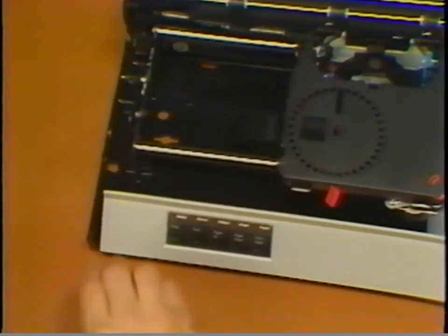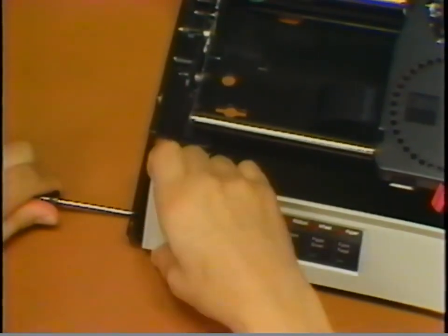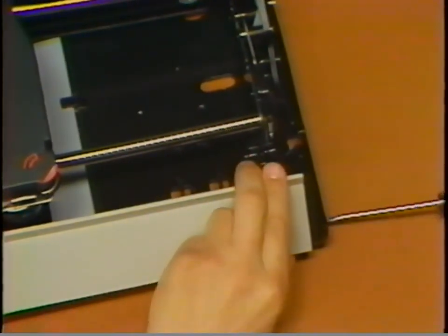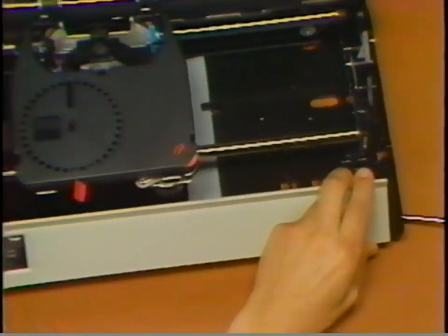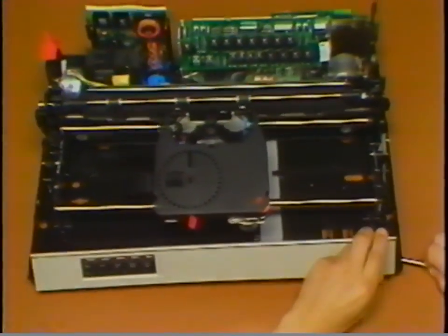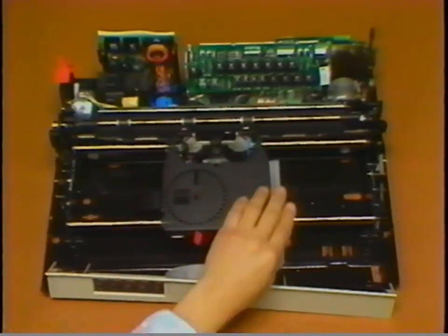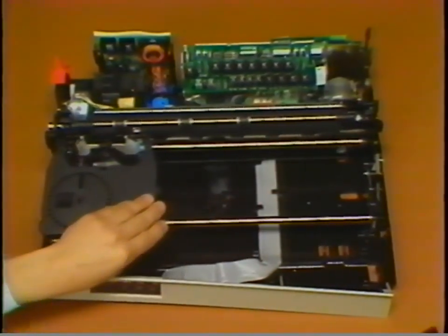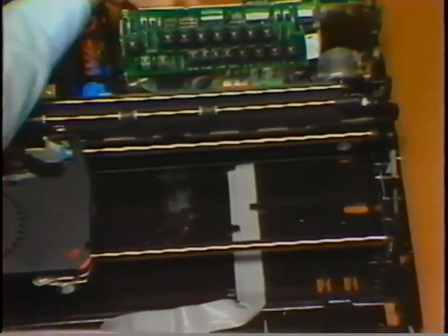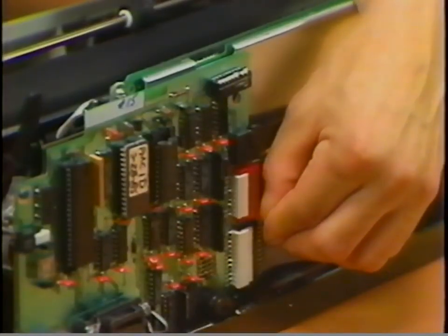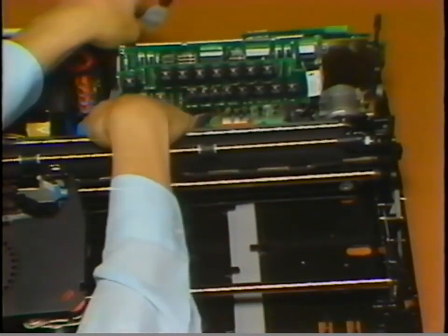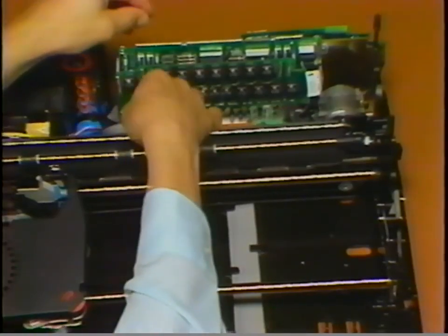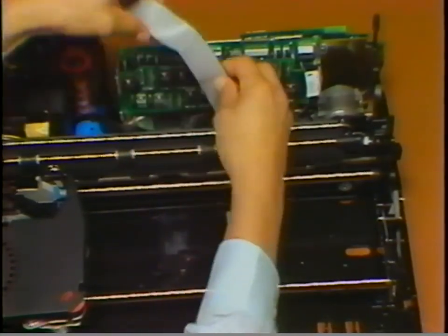The control panel is attached to the bottom pan by 2 latches similar to the cover latches. Release the control panel latches and remove the panel. Disconnect the control panel connector from the function board at the rear of the machine. Next, carefully pull the cable connector under the transport mounting bracket and out of the machine.